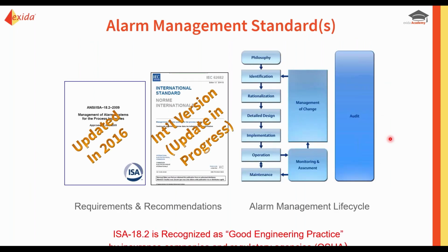So let's start with a mention of the ISA 18.2 and IEC 62682 standards that govern alarm management if you're a process industry plant in any part of the world. Both of those standards define the requirements and recommendations, as well as a workflow process called the alarm management lifecycle.